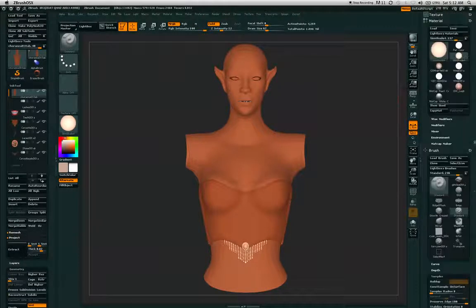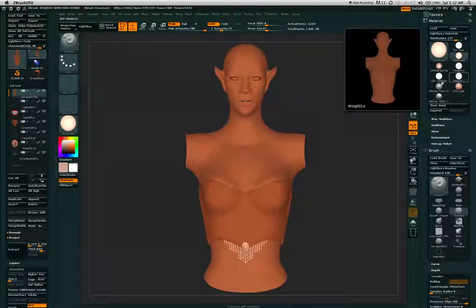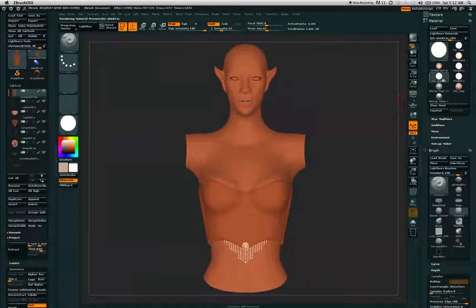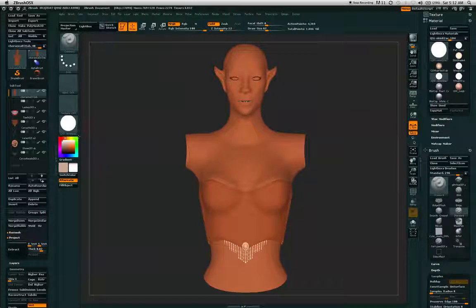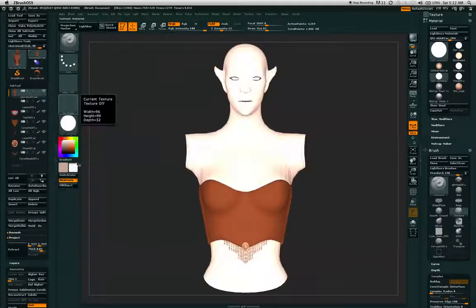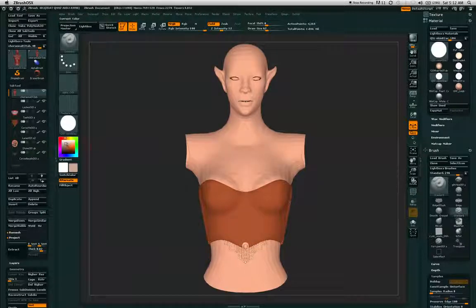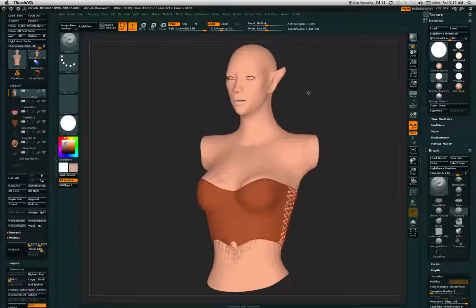The first thing we're going to do is we're going to select the material that you want to use on your model. And then we're also going to select the color. Once we have a color that we like, simply hit the Fill Object button. Now that material is embedded with the color into your 3D model.